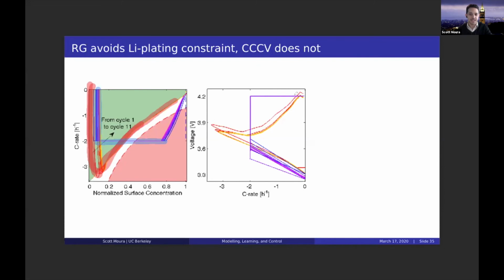Now, interestingly, if you look at the constraints as defined on voltage and current, CCCV is essentially setting this constraint boundary, right? We've got this upper and lower limit for voltage. The voltage lower limit here is slanted because it depends on the current that you're applying. Now, this constraint is really a proxy to try to not violate the lithium plating constraint and other things.